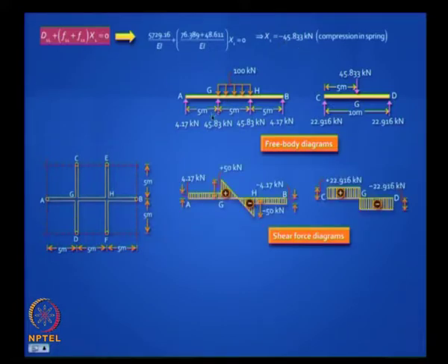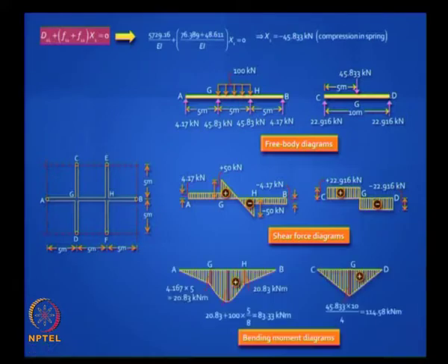So you have a force acting here, and the same force acts downward on the supporting beam. Is it clear? And these diagrams are easy to draw. You can draw the shear force and the bending moment diagrams. This is complete. So all you had was one unknown x1 and x2 was equal to x1. You can solve this problem. So this is how you deal with elastic supports.